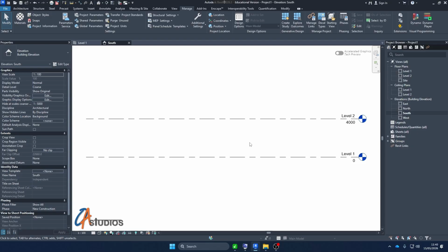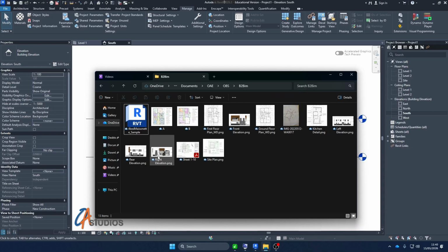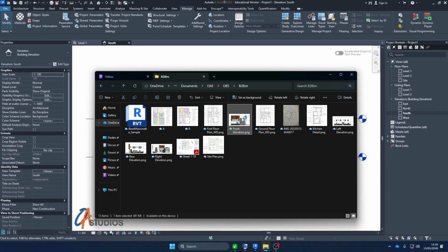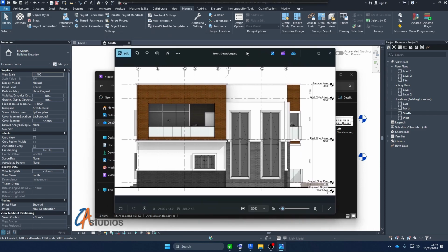Okay, so I'll set up the levels. From the files we have, I think I have some elevation files there. Let me see what was done previously. Okay, in the previous model we had assumed ground floor at 0, ground floor at 450, first floor at 3750, wall plates at 3.6 and parapet at 1.2. So we'll just stick to that.